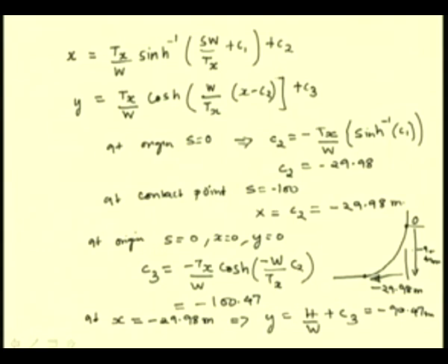So, these examples show how to compute the shape of the cables loaded uniformly along the cable or uniformly along the x direction. We have to use sometimes the differential forms because sometimes the end conditions are known in terms of the tangents or their locations.